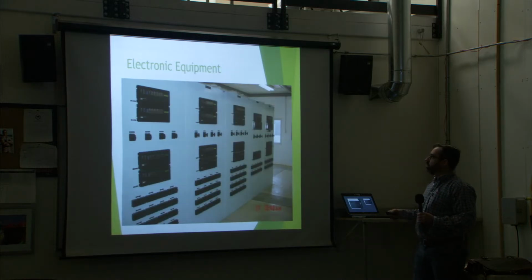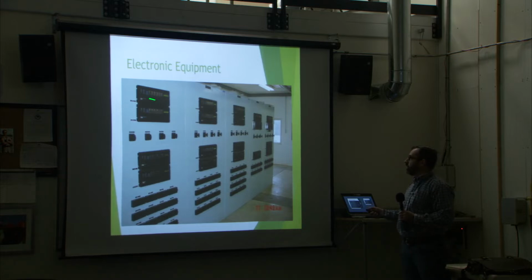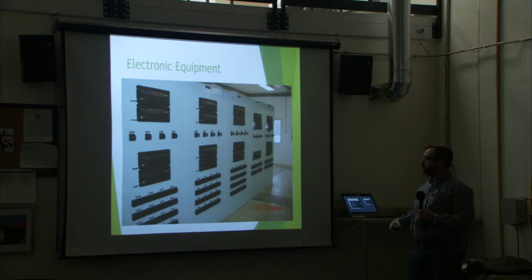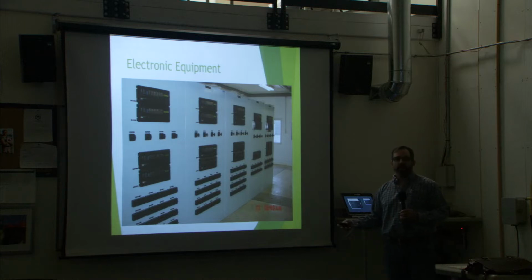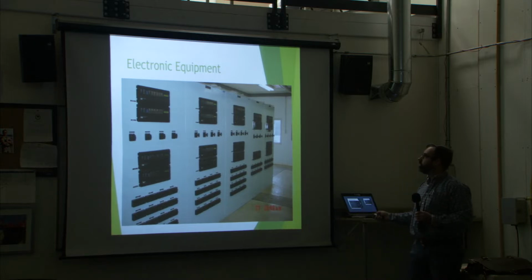So inside the control house, this is a typical relay panel installation. We've got protective relaying here and here. This is used for either line differential, some bus differential. Some of these are feeder protection relays. You've got your control switches for opening and closing breakers. There are some lockout relays in here, and then down at the bottom you'll see all these little panels. These are test switches for isolating our protective systems, our protective relaying equipment, from the system, so we can do testing when necessary. We can input voltages and currents through all these test switches here.